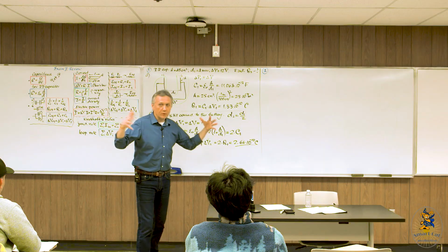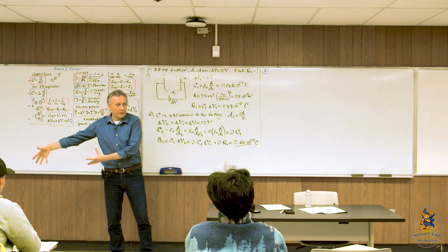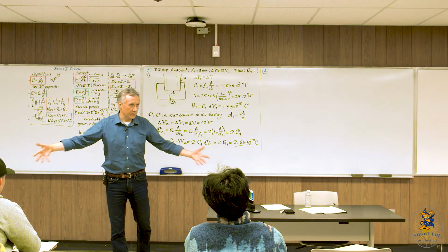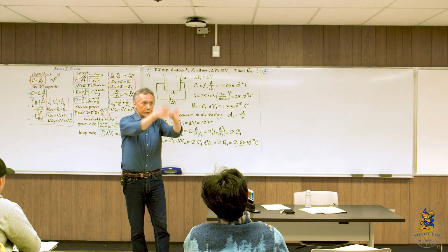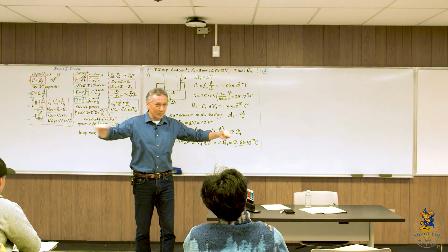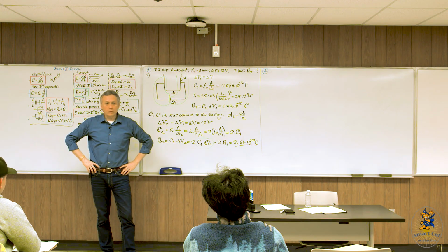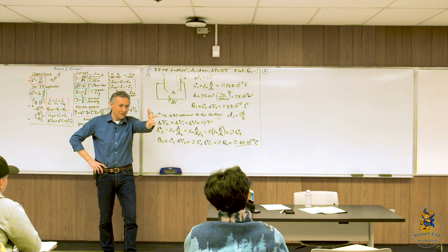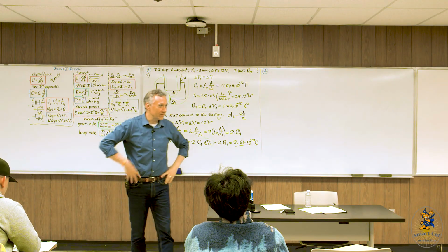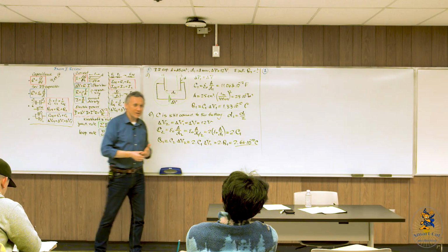Essentially, you can take that piece of wire, measure the length, measure the diameter, then grab some battery, whatever is available, apply it, and measure the current. Voltmeters, multimeters are everywhere, so you can easily do it. So, delta V, geometry of the resistor. You should be able to calculate the resistance, and then what do you need to know in order to find information about the material? Resistivity, not density. Density was the mechanical approach. Here, we need to find resistivity. Find the resistivity, then open the reference book and look for the material which matches your number.